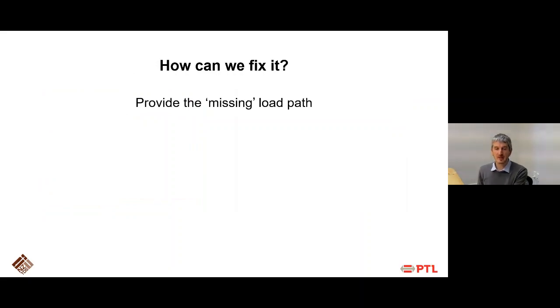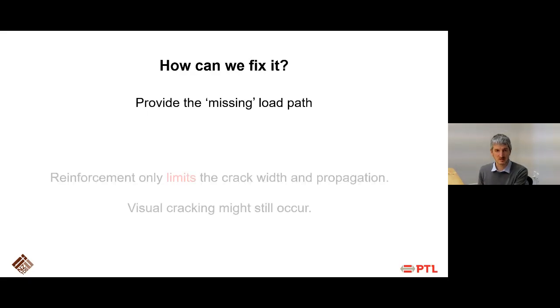What is the idea behind that? Now that we know that timber is not able to resist tensile perp-to-grain stresses, a bit like concrete, we can provide reinforcement with the use of screws, glued-in rods, and panels. They are providing the missing load path.